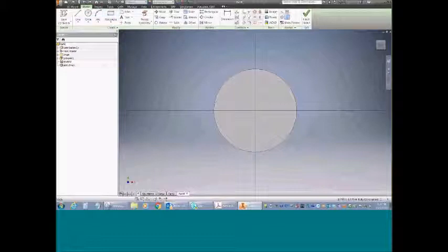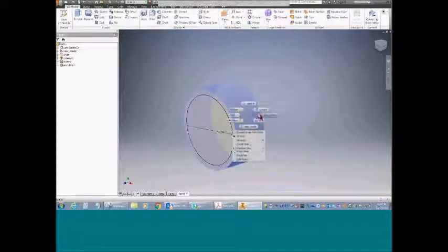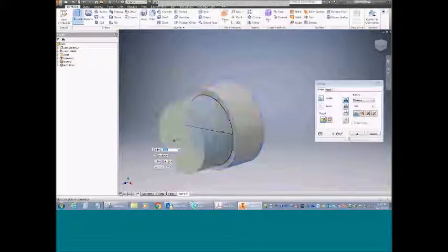And I'd also show them that they can just simply latch it down to the origin. Since my first one was latched down to the origin, the second one can be latched down to the origin. And that has a diameter of 1.75. We'll go ahead and finish that, and we'll extrude it. And that extrusion should be 1 inch.